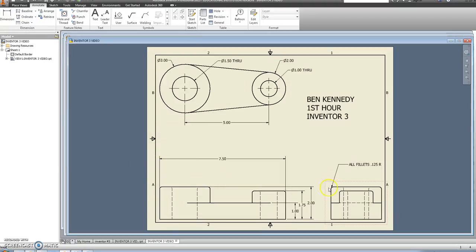This is how you do the fillet. That was a question some people had on it. Might be better off putting that over here, but as long as it's in there and you can see what you're actually dimensioning, you're fine. Baseline dimensioning here. Most of your dimension is going to come off the top. So that's it in a nutshell. I'm running out of time on this once again, so I'm going to wrap it up. This should be completed like this, snippet of it, then uploaded into the LMS where that assignment's located.